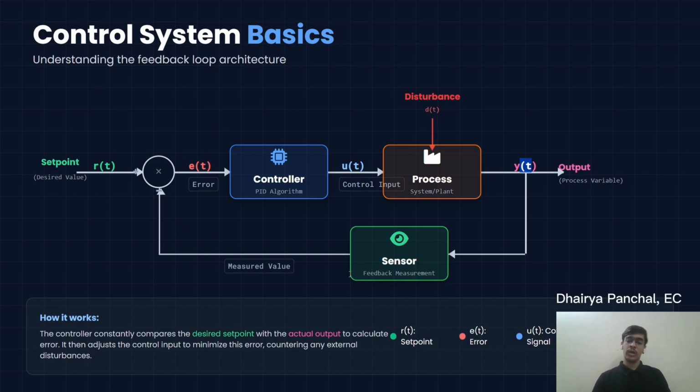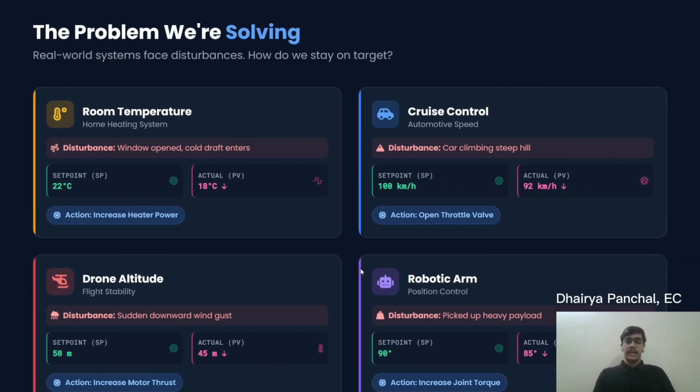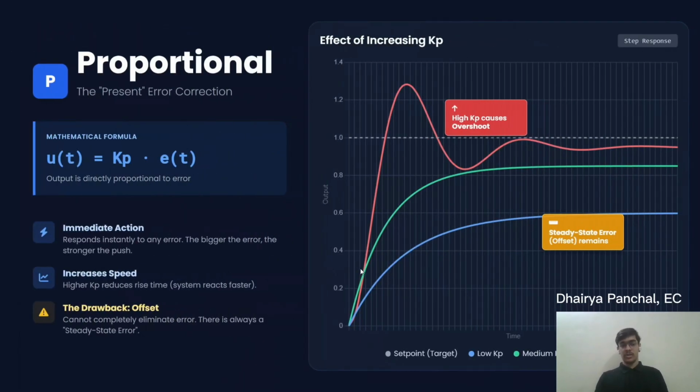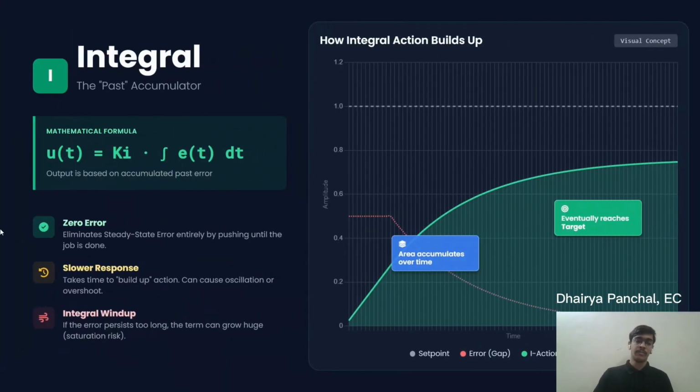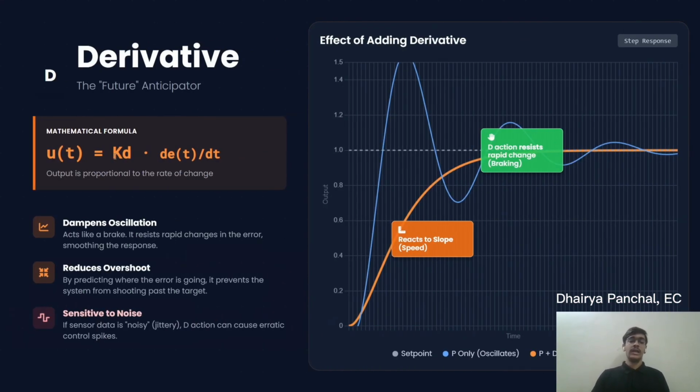So this is how this is a model of a PID controller. Once again, these are its applications. How does a proportional controller look mathematically? It's just multiplication with error. Then your integral controller is integral gain, that is KI, multiplied by integration of error, and your derivative controller is differentiation of the error signal multiplied with the derivative gain.